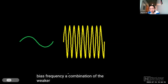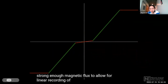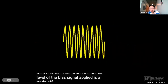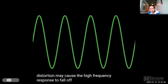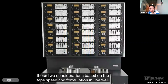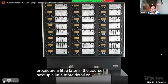The combination of the weaker, low-level audio signal and the stronger, inaudible bias signal provides strong enough magnetic flux to allow for linear recording of the low-level audio, reducing the otherwise objectionable third harmonic distortion. The actual level of the bias signal applied is a trade-off. The optimum level for minimal distortion may cause the high-frequency response to fall off, so the bias level is set for the best balance between those two considerations based on the tape speed and formulation in use. We'll see how to make this over-bias setting when I cover the tape alignment procedure a little later in the course. Next up, a little more detail on the tape heads.